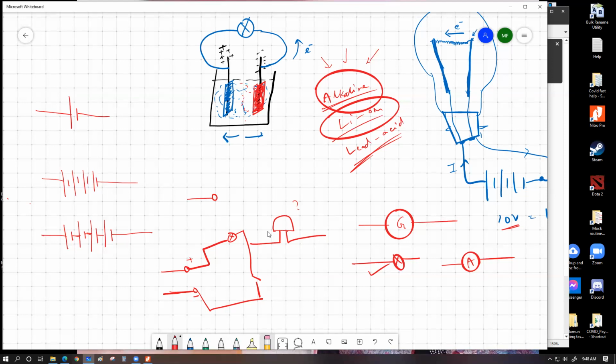What technology operates this power supply is none of our business for the time being. This might be made available from an actual battery. This might be two connection points out of a potential divider circuit. This might be a connection point out of an AC to DC converter, by full wave rectification and capacitor smoothing. These two circular things, which are now working as the energy source for the electrical circuit, might be made available in quite a lot of different processes.